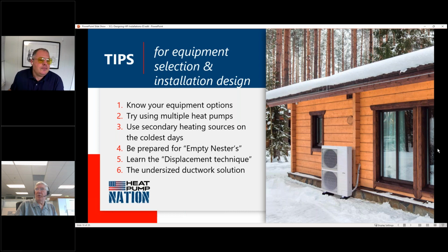Okay, a couple more real quickly. I think one is, and the second will be a kind of a segue. One is asking about a blower door test. Does that give any valuable information for calculating heat pump sizing? And my recollection is that might be required by Manual J. It's not required by Manual J.